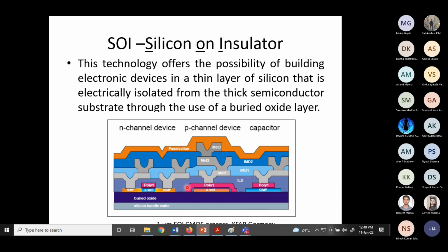And in fact, you can remove silicon in some places. You see here, there is an oxide layer, ILD, insulating dielectric layer, basically an oxide layer. There are other dielectric layers also that people use between different devices. So here you see, if you etch out silicon in between the devices where you don't need silicon, you will be able to reduce the crosstalk between devices, because there is no silicon. Whereas that you can't do if you have a conventional CMOS or silicon wafer, because you can't etch out silicon between devices, because all through that is silicon.